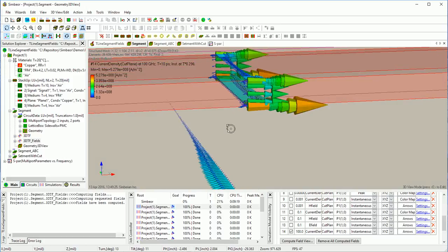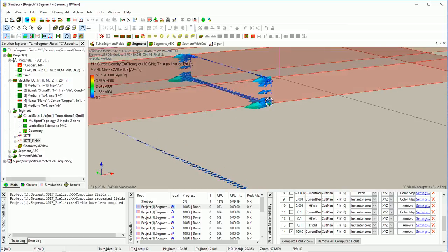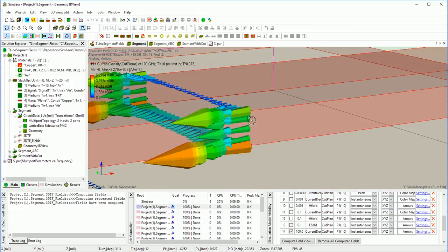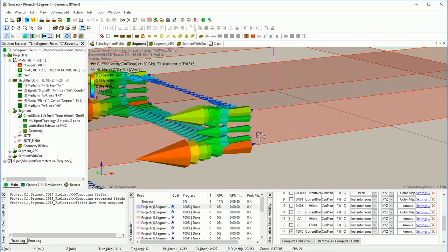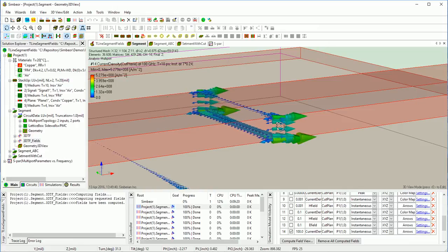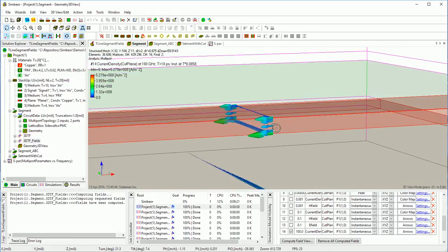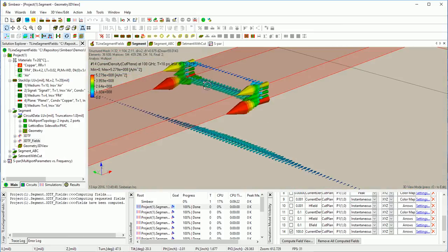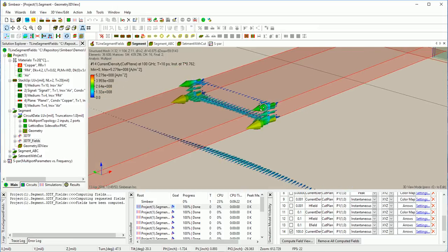It's barely visible. In addition to all the other effects of current lagging behind and a really small layer on top, we can also see wiggling: the current direction is not exactly along the edges, it goes up and down slightly due to high order modes, redistribution of current between the bottom and top part of the microstrip.